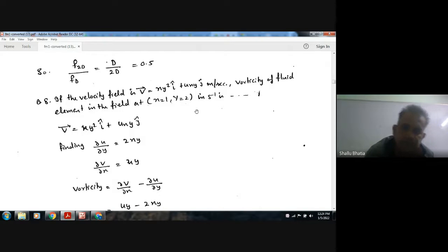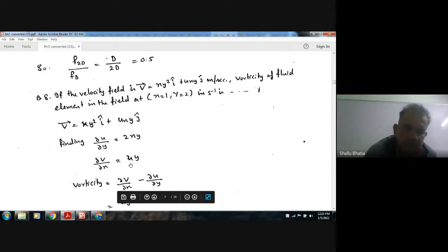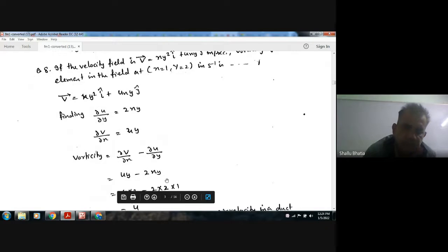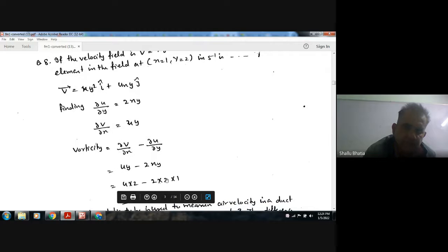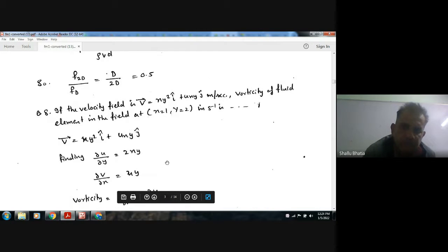So vorticity is ∂u/∂x. Oh, sorry, ∂v/∂x minus ∂u/∂y. And ∂u/∂y, where u is xy², is 2xy, and v is 4xy, so ∂v/∂x is 4y. So the vorticity is the difference of the two. Putting the values, 4y minus 2xy, and putting x = 1 and y = 2, we get 4. Answer is there. Okay. Next.